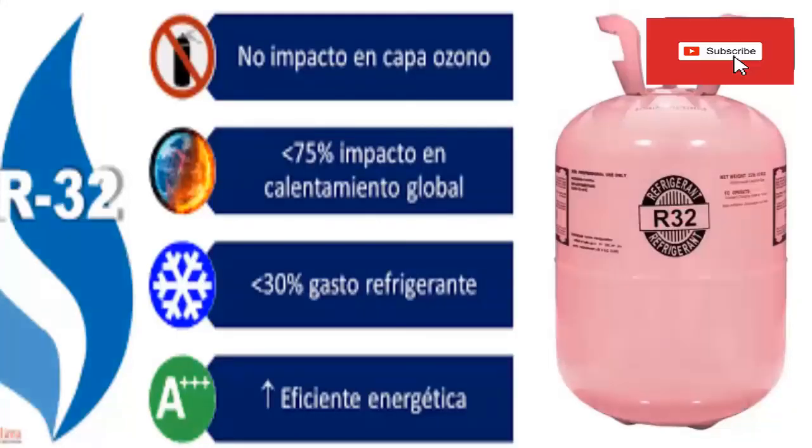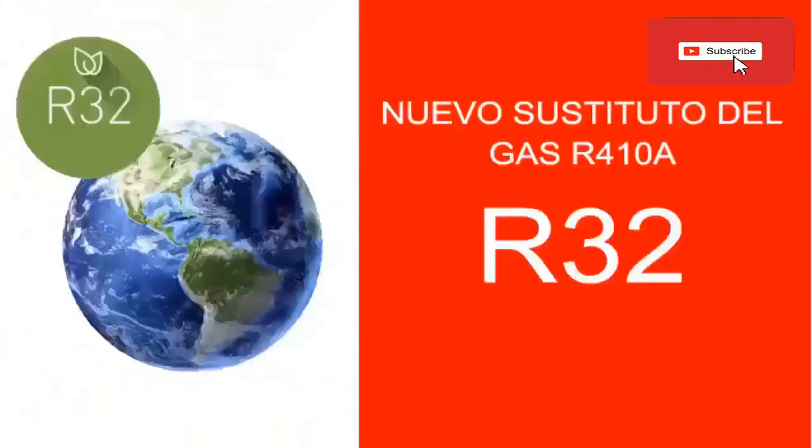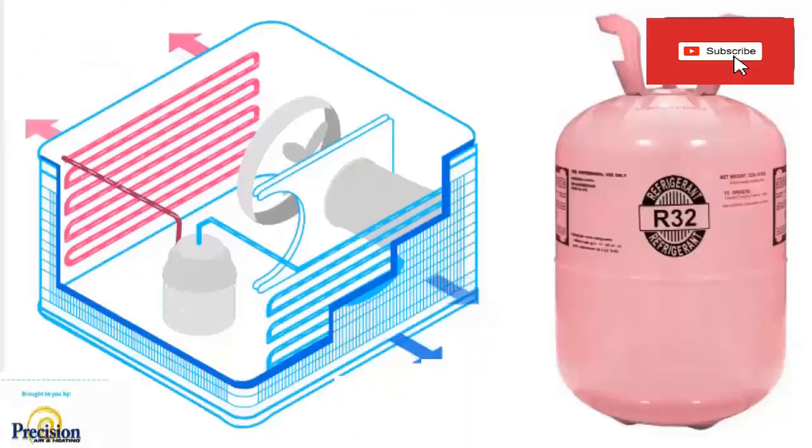Let's start by saying that R32 is not a replacement gas for R410 in equipment that is working, but should only be used in new equipment, specially designed for this gas.